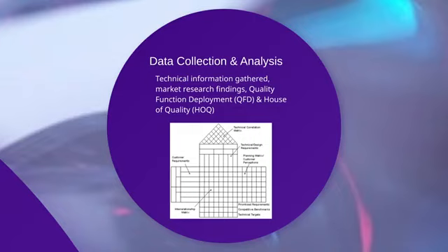Okay, and the house of quality here in the diagram helps us in the quality function deployment method. It helps us to identify the customer requirements and interrelate them with the engineering requirements, as well as it makes a correlation matrix between the engineering requirements themselves. It relates the engineering requirements to each other, how they affect each other. And it uses benchmarking as well to compare the current design with other similar designs. There's also a prioritized requirements section in the bottom, which informs us about the importance level of the customer requirements compared to the remaining customer requirements.